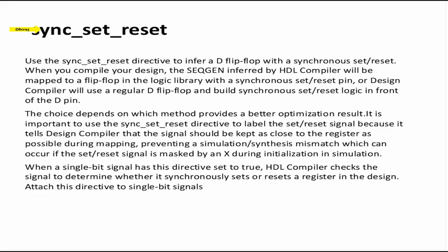This is not an easy example to explain right now, at the level when you are starting to learn synthesis, but as you go on, you will find that this is a problem in big designs, where you have complex synchronous sequences. So, if your synchronous reset is being generated by some complex logic, and you want to keep that reset close to the flip-flop, then you use this.